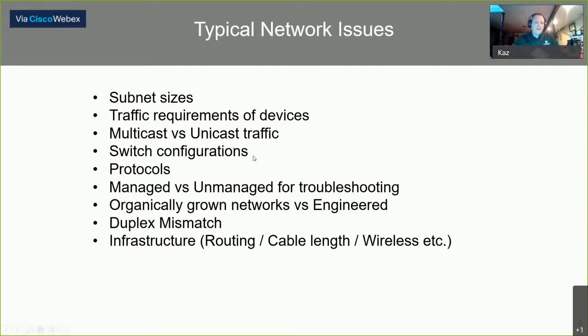Switch configurations. I can't tell you the number of times that I open up a panel and see a managed switch there, and I ask what the IP address is of that managed switch. And one, they can't tell me what the IP address is, so nobody knows, so documentation of the network is poor. Or two, they know the IP address, and then when we go to log on to the switch to do some diagnostics, it's got the default username and password, and it has never been set up. So a managed switch that has never been set up is basically an unmanaged switch. That acts as an unmanaged switch. So configuring your switches properly is important.